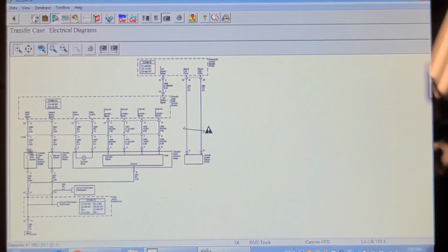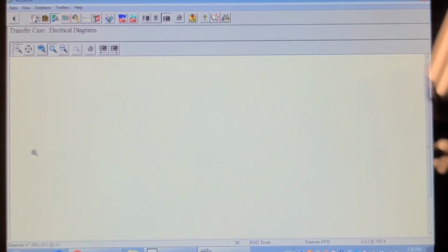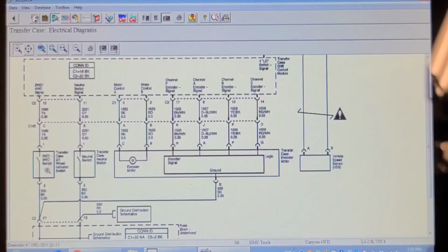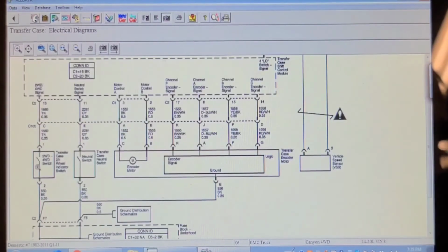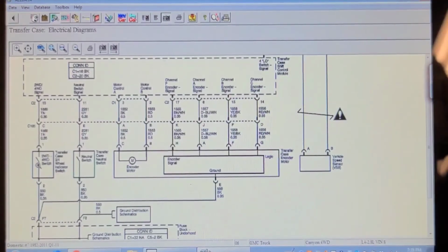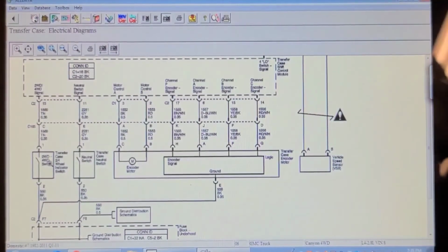Okay, so here's what I'm going to do. When I backpin this two-wheel drive, four-wheel drive switch, I show about 12 volts on the wire, and it should go to ground when it's in four-wheel drive according to everything I've read, and it does not. But I'm sure that switch is defective. The transfer case is physically going into four-wheel drive, but it won't stay in there because this switch is not indicating it. It's not setting any codes.